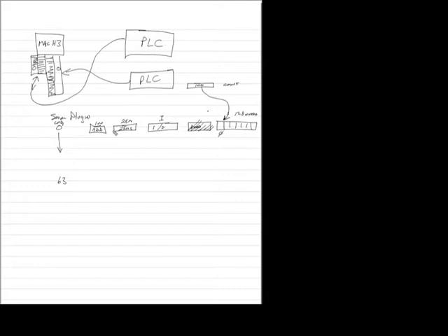By default, every time you transfer something into a configuration area, the first register goes into word 0 of the 128 words. If you tell the configuration that you're going to transfer 7 registers, and you started at address 100, then the PLC will transfer from 100 to 106, that's 7 registers, and transfer them 0 to 6 inside this area. If you watch the brains and MPGs, you'll then see how to get any word or bit of data from any one of the 63 configuration areas.